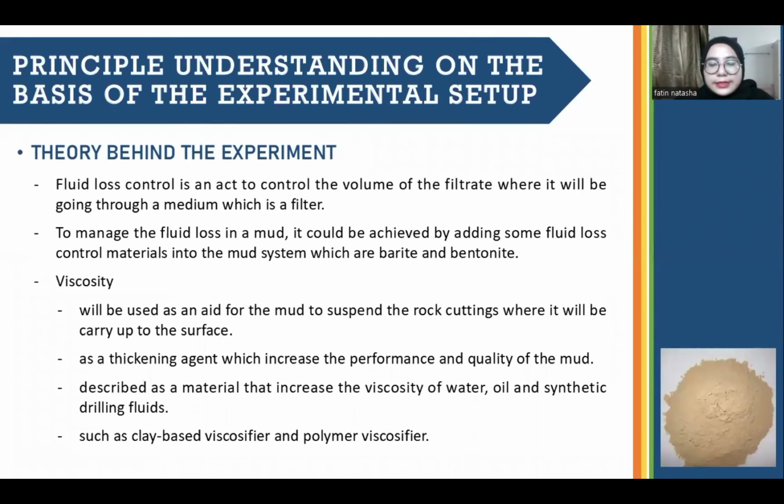Viscosity will be used as an aid for the mud to suspend the rock cuttings, where it will be carried up to the surface. A viscosifier, also known as a thickening agent, increases the performance and quality of the mud. It is described as a material that increases the viscosity of water, oil, and synthetic drilling fluids. There are various types of viscosifier, such as clay-based viscosifier and polymer viscosifier.